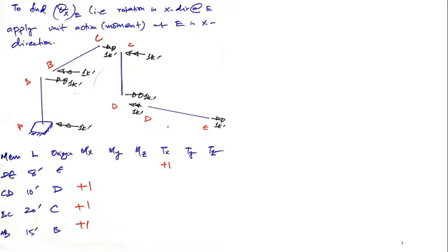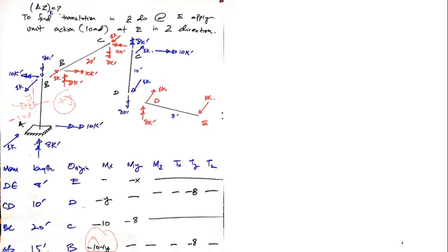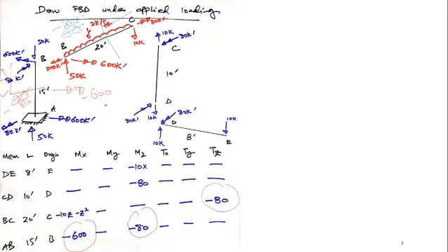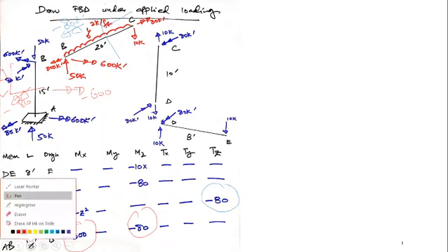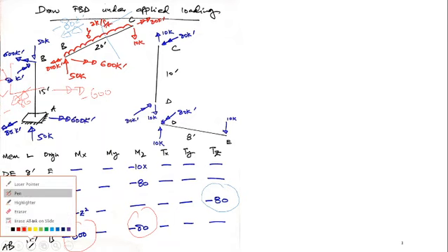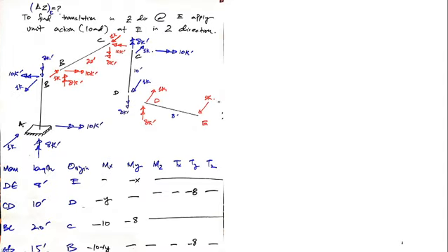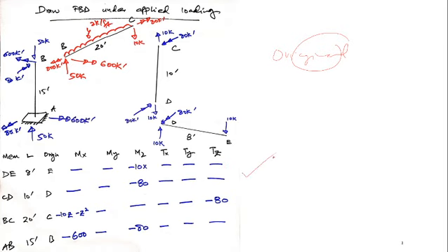Okay, finally, before going to calculate, if I have to calculate the translation in Z direction, what I have to do is multiply the respective elements of these two tables, because this is under original loading, and this is under a unit action in Z direction at point E. So if we multiply the values of this table with this, I'll get del Z at point E.